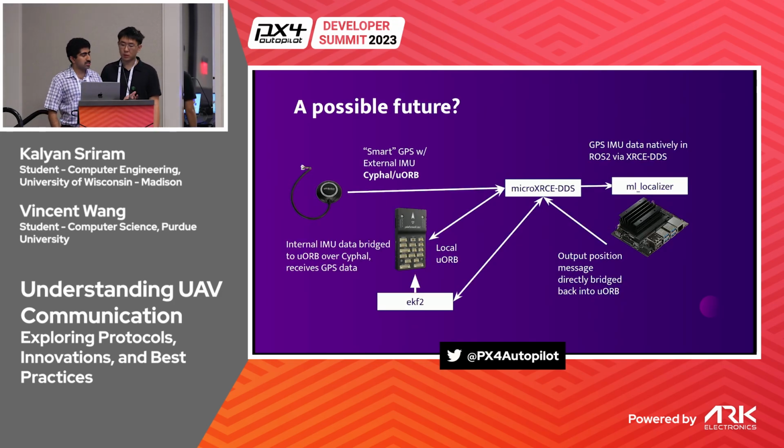Ideally, this could actually be extended to CAN networks too. Imagine for a minute if any device on your CAN bus could exchange messages natively with UART and DDS, furthermore cutting down on the need for special drivers and a lot of transcoding. This would also let us split PX4 up into multiple hardware components, which could be useful in the future for redundancy and performance load balancing.